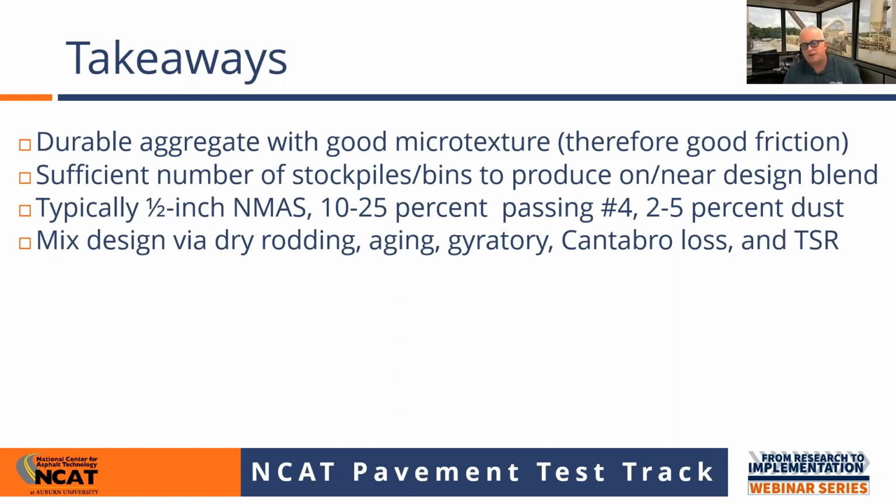So as Jim said, just to kind of do a really high altitude review, you've got to do the dry rodded unit weight. You've got to age the samples. You use a gyratory compactor to put samples together, measure the loss in an LA abrasion machine. That's called Cantabro loss, and then run moisture susceptibility testing on the mix to make sure you're not going to have a stripping problem. And the good news is this is all stuff that a contractor can do on the front end of the bid.